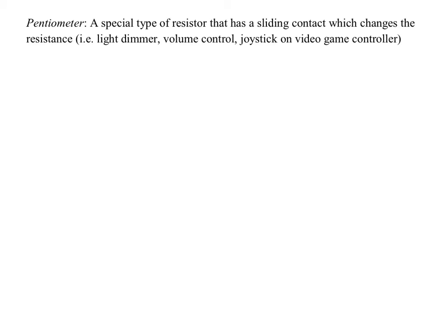Now, another example of that, video games, joysticks. A joystick is sensitive, especially newer games, maybe not old school arcades, those were pretty basic. But like a new Xbox or PlayStation, the joysticks on them, and you probably know this from any game where you have to aim. If you move a little bit, the aimer will move a little bit slow. If you move the joystick over to the right, the reticle will move much faster. Okay, it's a potentiometer. It's a variable resistor. And the same thing for, I think the last example was a volume control on a speaker system. Okay, so a potentiometer, it's a special type of resistor that's used widely. And the reason it works is because you have a sliding metal contact that takes on more or less area. Depending on how much area of contact there is, the resistance in the element changes.